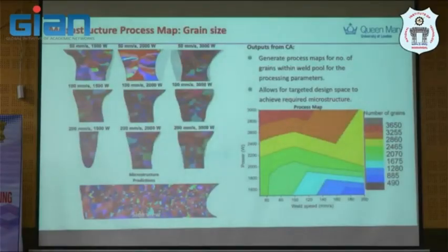So now we map the grain size. This is all predicted. So this is the predicted grain size from the condition that I proposed to you. So this is a PV map, so P power and V velocity. So you can again see the same: you get the hot spot, and you get the sweet spot for this processing.